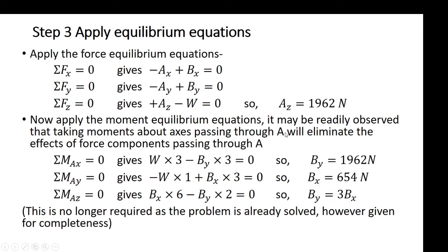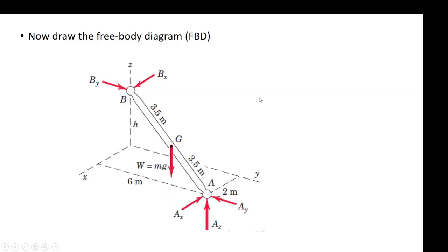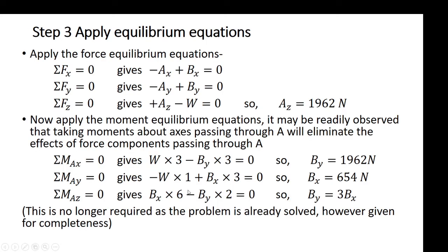Apply equilibrium equations. Without thinking what will be most convenient or useful, I have written down the equilibrium equations straightforwardly. First, force equilibrium equations, and then moment equilibrium equations, and then see what happens. I think, students, you can make out what we have done. I have accounted for all the forces acting in x direction, y direction, and z direction, and also all the moments acting around the axis.